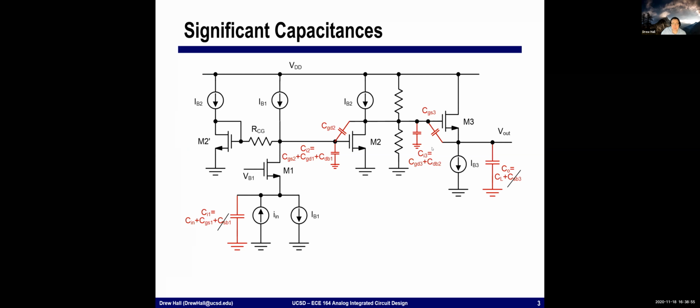Okay, so the first thing that I'm going to do is look at the capacitances in this circuit. What I'm trying to do here is identify and position all of the poles. At the input, I'm going to have some capacitance from this transistor M1. I'm also going to have the input capacitance from this input source that's given to me as Cin. And then I'm going to start to make some assumptions. Again, the idea with my first cut design is not that it's perfect. I want it to be within, call it, 10% of the design target.